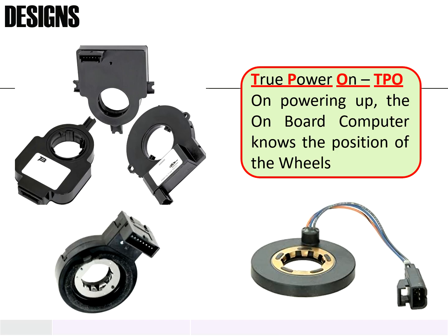One important sensing technology used in this sensor is the Hall effect. We have already seen the Hall effect principle in the previous class. A multipole magnet is fixed to the steering column. Hall elements are used to detect changes in the magnetic field.